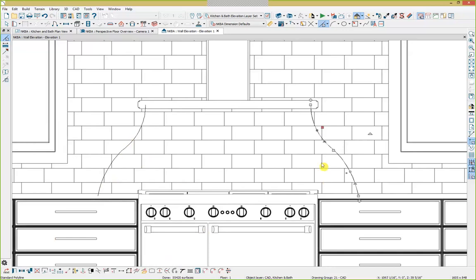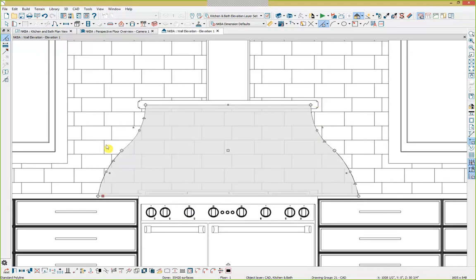So there we've got that other CAD line on the other side. And then you'll notice that there are extra diamond handles here as well. We've already learned that you can use those handles to add things to your design. So what we're going to do is extend the line to the other side over here. What we've formed there is a solid CAD polyline.